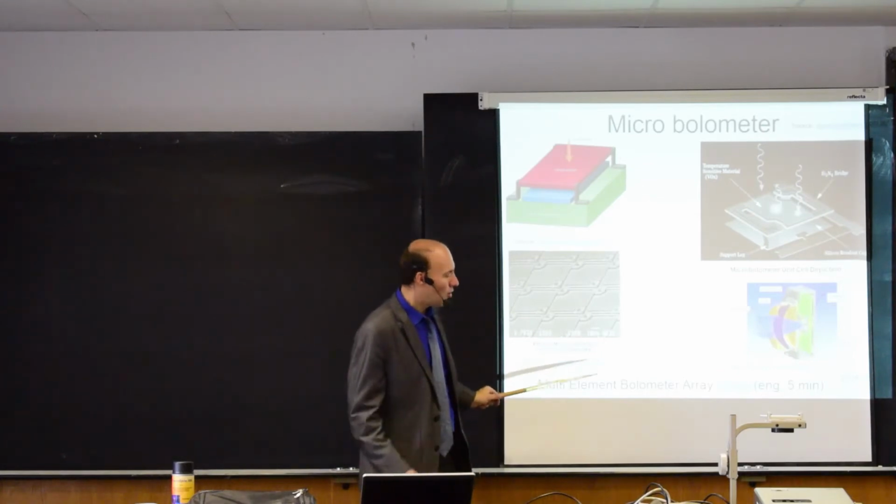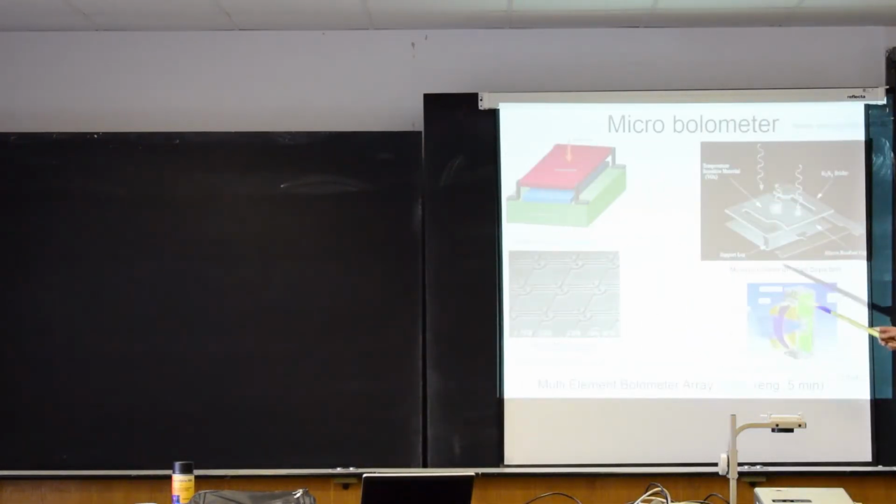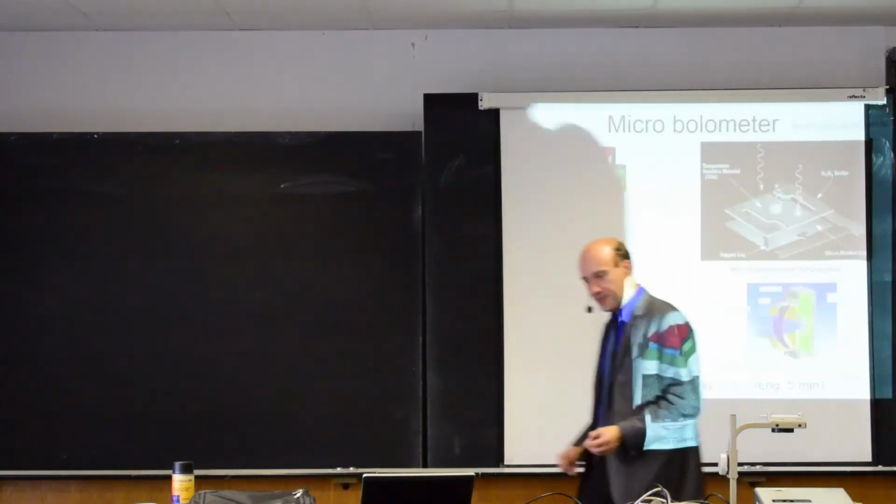And the whole bolometer is then arranged on a chip. And here we see the optics from the materials, germanium lenses. And here this is the bolometer, and it's acting like a CCD chip in a camera. The difference is that here we detect infrared radiation. With a CCD chip, we detect visible light.